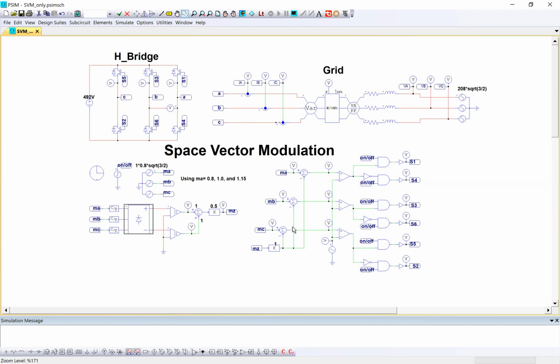That way you get rid of some of the harmonics that end up arising when you're doing power engineering. Because if you didn't know, if you have harmonics in your system, you lose efficiency and you potentially are losing out on more energy that can be used. So we have this system in place to regulate a couple of the harmonics, specifically the third ones and any larger ones. The control system takes care of that.